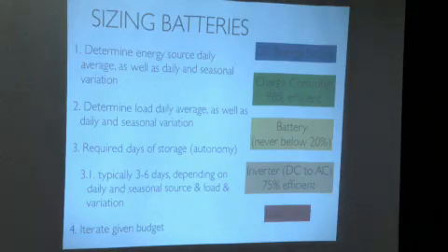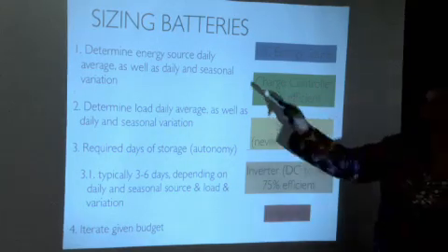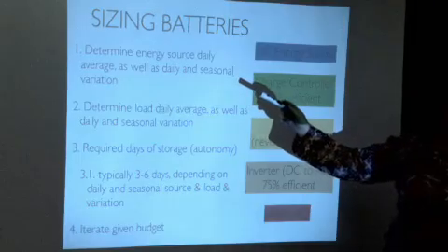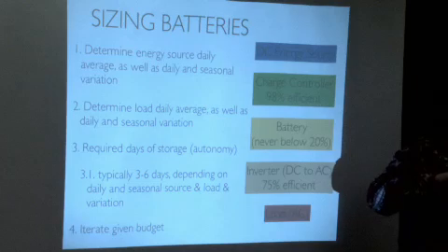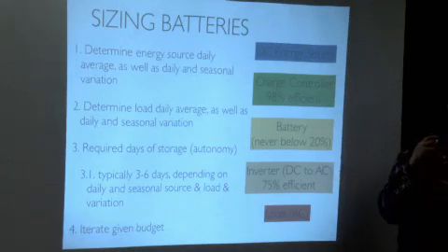And then, for just simply thinking about, say, a lead acid battery and how it's going to integrate into your system and how you size it, you figure out what your source is, and you have to think about both your daily average as well as your peaks and lows on a day-to-day basis and a seasonal basis.